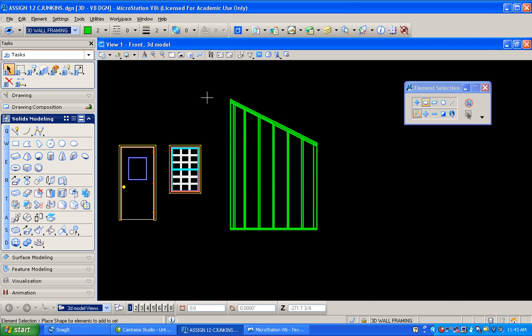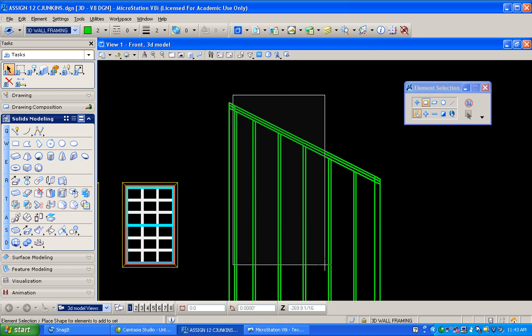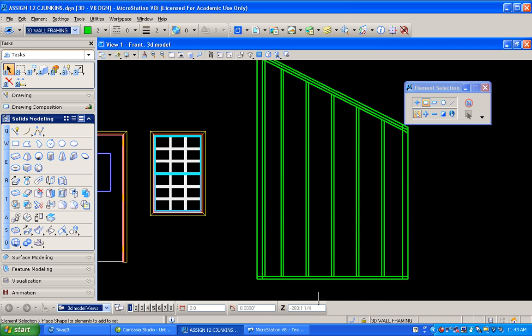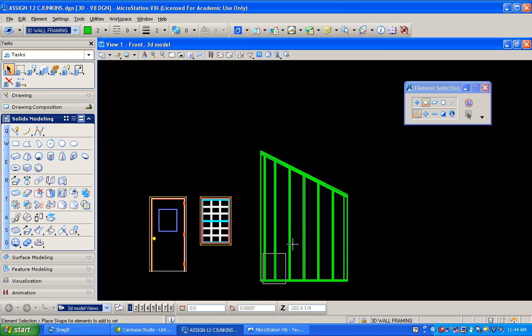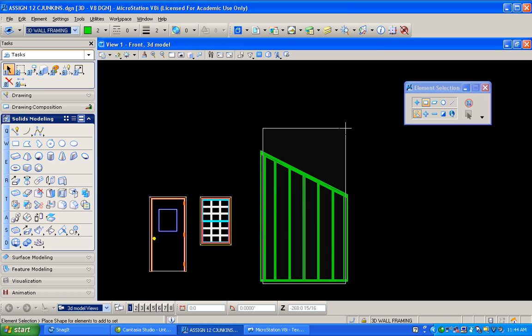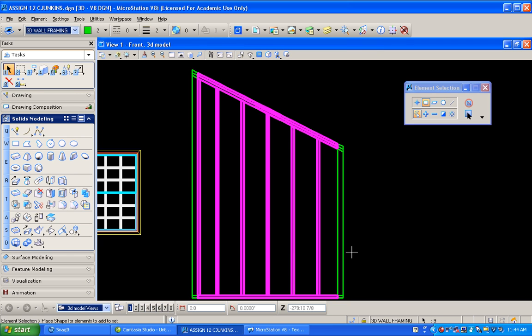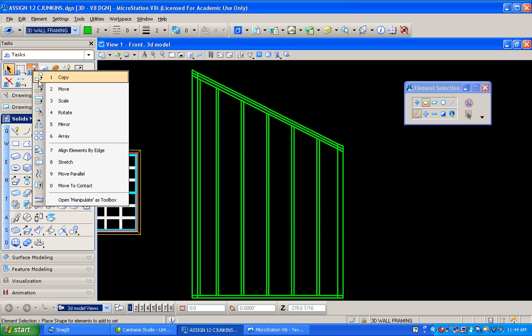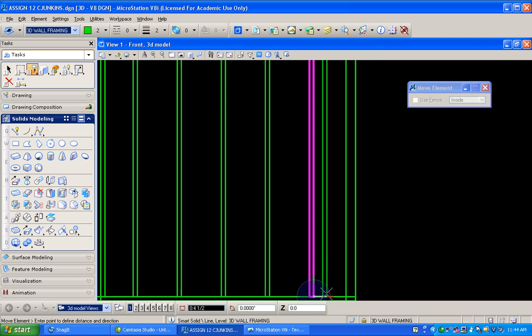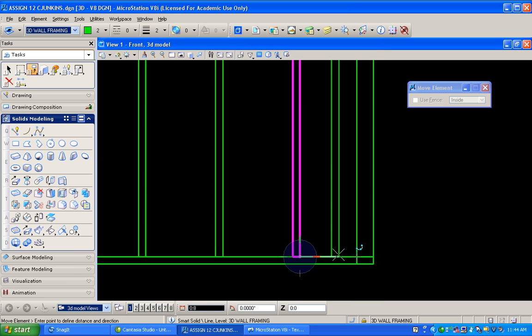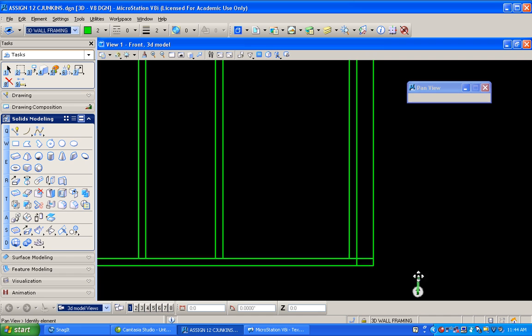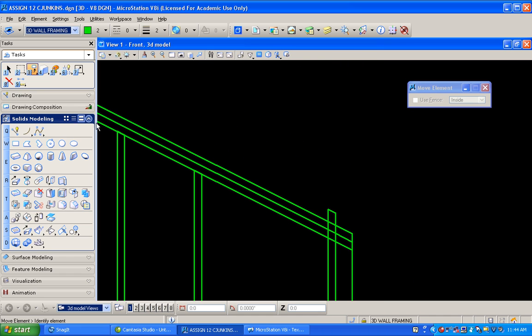We're going to take our selection tool and select, make sure I can see it all here. If I just stay inside the studs on either front to back wall, it allows me just to select that piece. And I can see I'm missing a stud here now, so I'll deselect that. We need to come down and place another one right up against this one, and then we'll cut it.